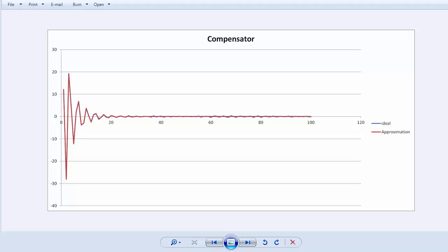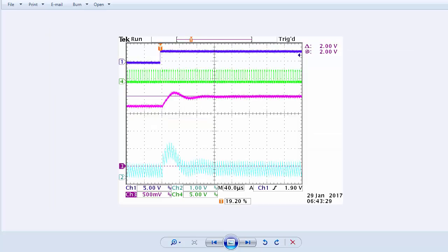Now, would I consider deploying this compensator in a released design? Absolutely not. This is a ridiculously aggressive compensator designed as an exercise to see what is possible in the extreme. For comparison, here's how the out-of-the-box compensator performs under the same conditions. This compensator uses 3 numerator and 1 denominator coefficients plus the integrator.